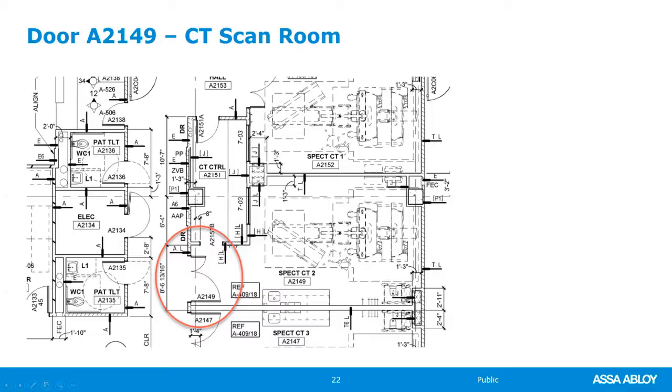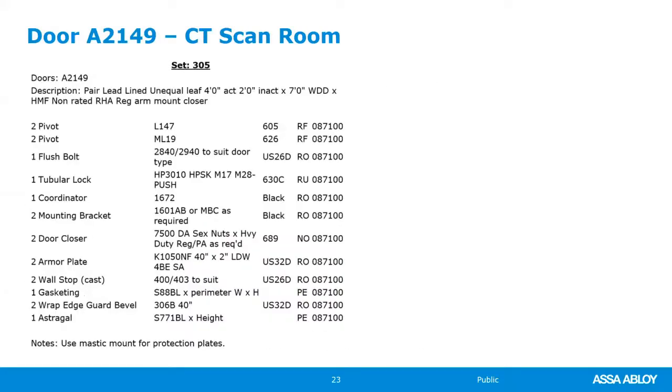You can see the L in the wall type. You could look that up to figure that it's 1/16 inch lead. And depending on where the lead is within the door, the lead could be either centered in the door or it could be underneath each veneer on the outside. That does affect your hardware options and what you choose. I like to hang heavy doors like this on pivots. It takes all of the weight of the door and puts it into the floor.